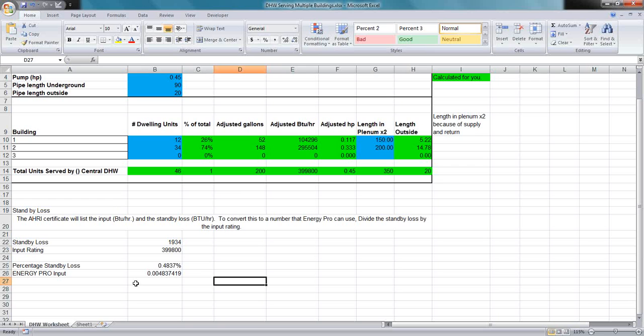Next question is, and I'll send this one to you, Kyle, can we do a power draw on existing pumps and use this to estimate the actual brake horsepower? Yeah, if you can document it and you're getting the right power draw of the operating conditions.